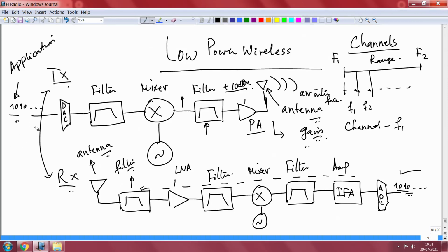150 meters. Well, it is not going to work that way, because your transmission power was only kept at 10 plus 10 dBm. It can only have a finite distance over which you can actually receive the data. You can't infinitely keep increasing the distance. You have to do other things in order to get to 150 meters, which we will not get into at the moment, because this basic understanding is what we are putting in place.